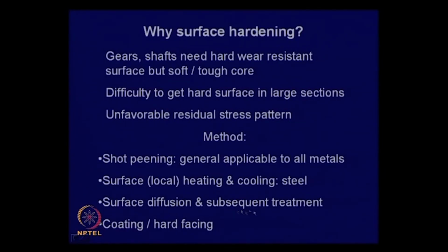There is another approach. Normally, in order to have a tough core, it is often necessary to have low carbon in the core. Low carbon in the core gives you very good toughness, and you can also give some special heat treatment by which you can improve the toughness of the core. The carbon is mostly present as cementite, and if it is present in pearlite, it may not have that kind of toughness.